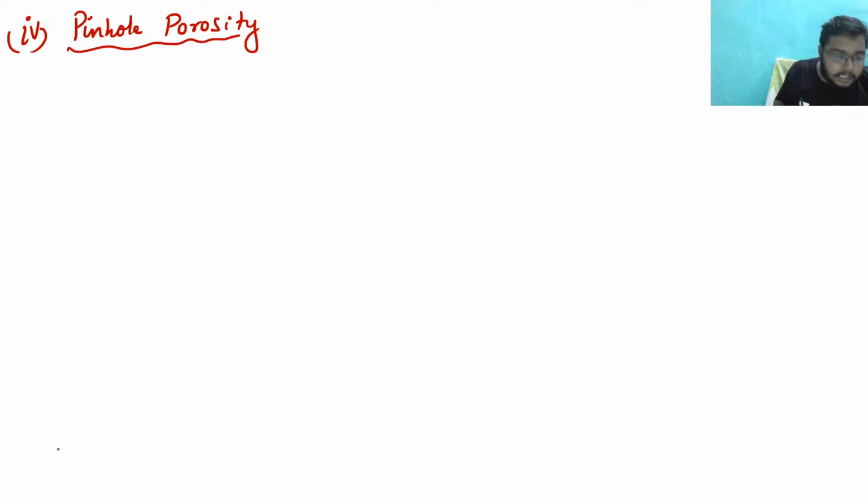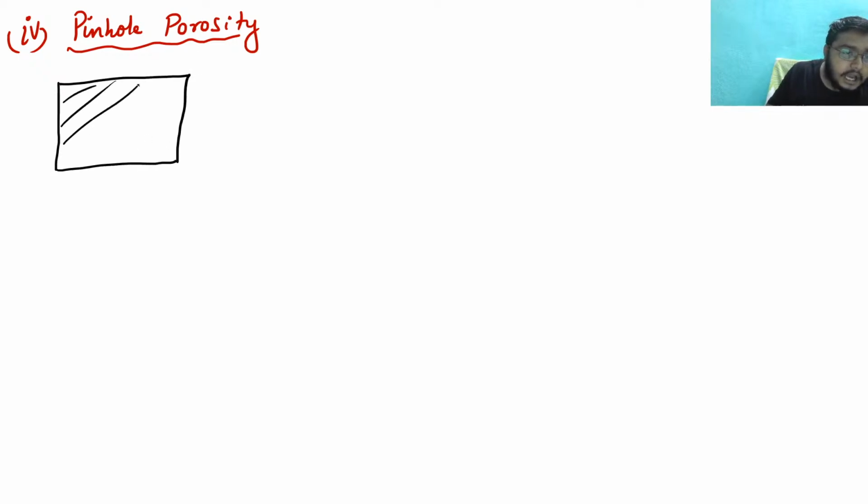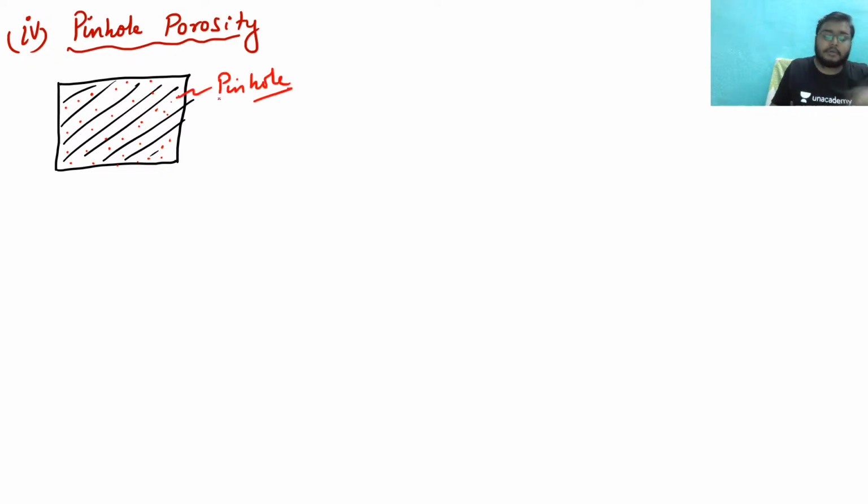Pinhole porosity. Now see what is the difference in this pinhole porosity. Suppose you are having the casting, right? So suppose this is my casting. Now in this entire casting, what is the difference in this pinhole? Very tiny amount of holes are present in the entire casting, and these tiny holes are known as pinholes. And we know that these are gas defects.